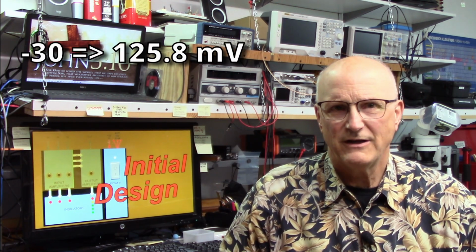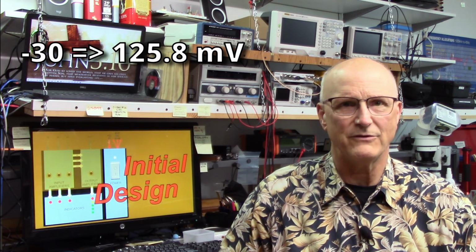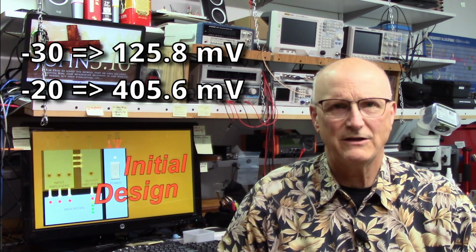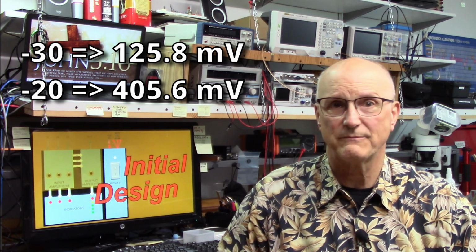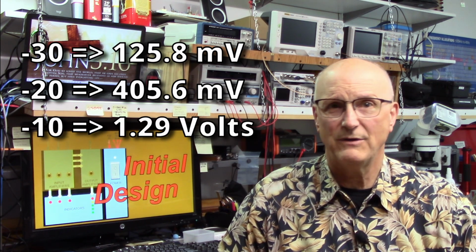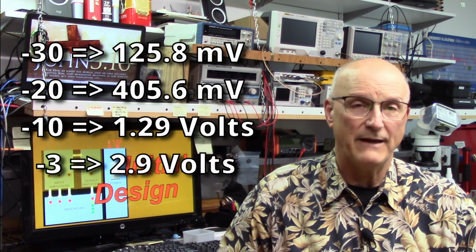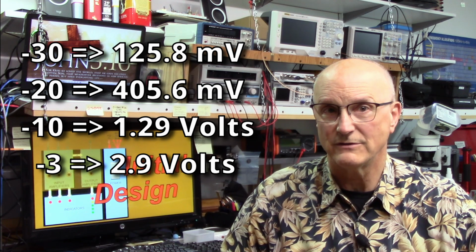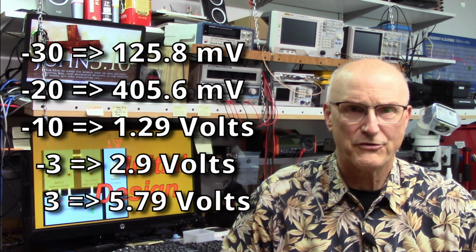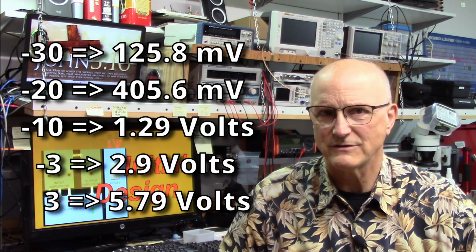At minus 30 dBu, we have 125.8 millivolts. At minus 20 dBu, we have 405.6 millivolts. At minus 10 dBu, we have 1.29 volts. At minus 3 dBu, we have 2.9 volts. At plus 3 dBu, we have 5.79 volts.